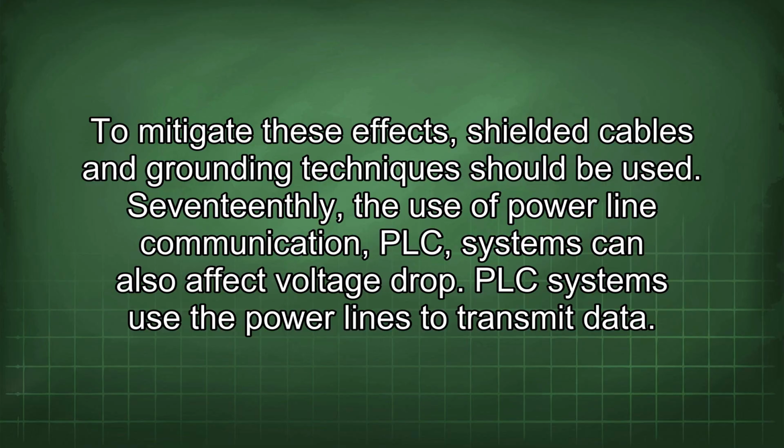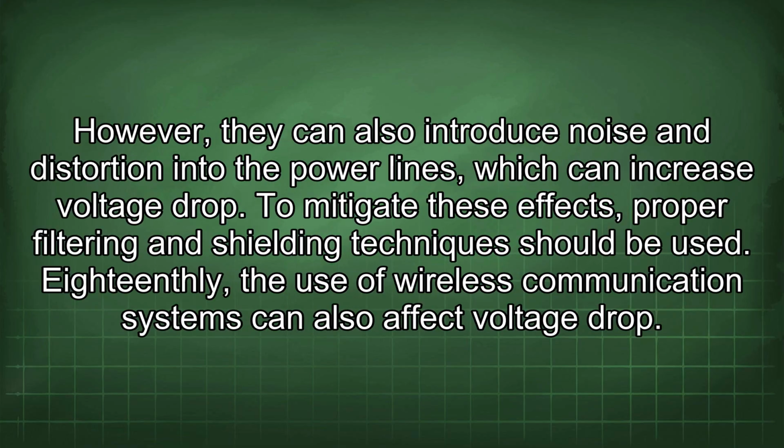17thly, the use of power line communication, PLC, systems can also affect voltage drop. PLC systems use the power lines to transmit data. However, they can also introduce noise and distortion into the power lines, which can increase voltage drop. To mitigate these effects, proper filtering and shielding techniques should be used.